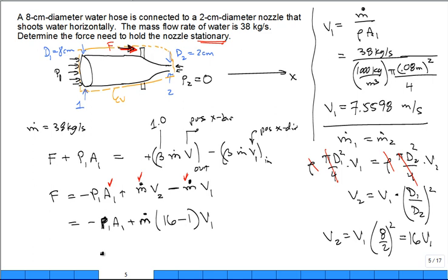All right, so we use the Bernoulli equation to go along a streamline from state 1 to state 2. Okay, and that Bernoulli equation had, I'll try and tuck it somewhere. Where should I tuck it? Put it right in here. How's that for use of word space? So it's P1 plus 1/2 rho V1 squared equal to P2 plus 1/2 rho V2 squared. No changes in elevation, so there's no rho g z. And this is 0, or atmospheric, or gauge 0.